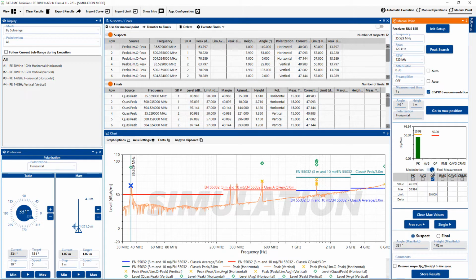Because we're in a range below 1 gigahertz, we're going to use the quasi-peak detector for that. And as you can see, because I changed to the quasi-peak detector, the measurement time came up to 1 second. It could be set to a higher amount, for example, if the peak was unsteady. And then I can say to do a single run, because that will measure it. It will do a continuous measurement in max hold, and will record that value as the final value after the measurement time expires. The previous measurement in free run would not stop until commanded to do so.